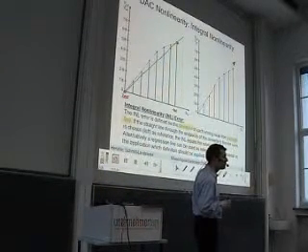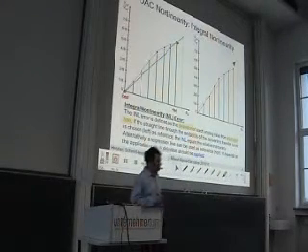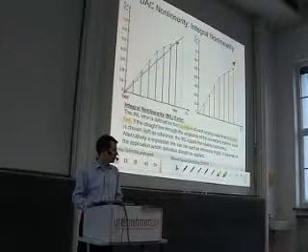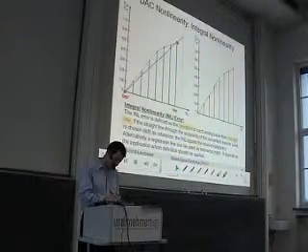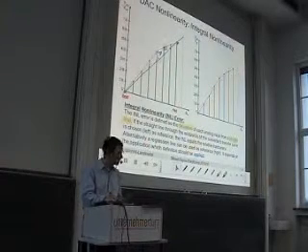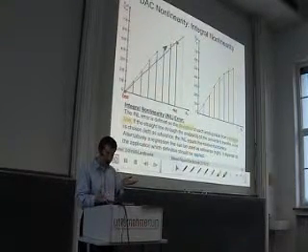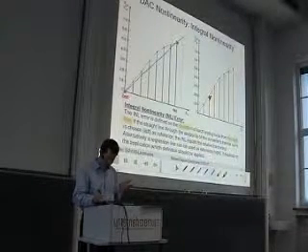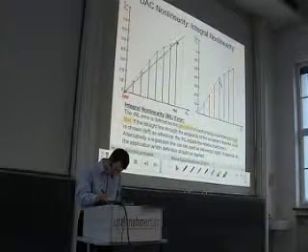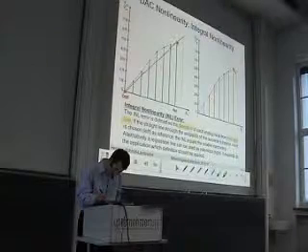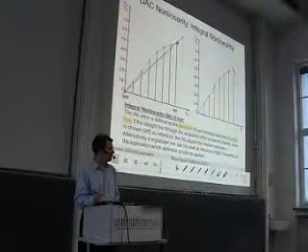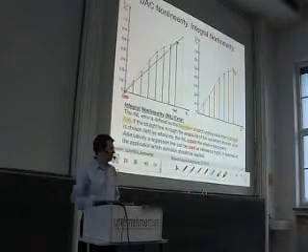Pardon me? Not exactly. The question is, if I take one or the other definition, does this give the same result? Here you can see in this curve the integral nonlinearity is always positive, so we are always above this reference line. Here not. So obviously, if we sketch the same values here, they are different. It depends a little bit on the application which one is better. Marginal differences.